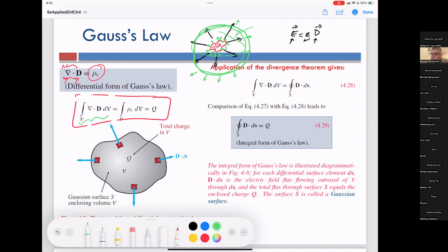So this is actually Gauss's law, although it's not fundamental. It's very useful. Honest to goodness, in our startup we were trying to figure out a capacitance issue the day before yesterday, and we ended up using Gauss's law to reason through what would be a reasonable value of capacitance. In my mind, the main usefulness of Gauss's law is the fact that you are free to define the surface away from the object.